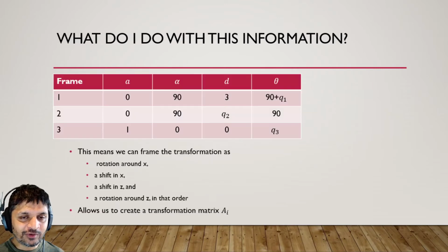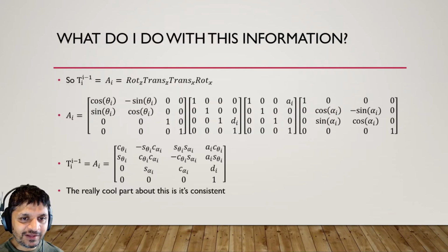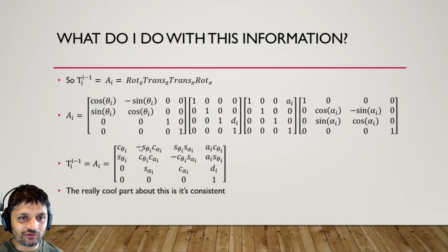Now, here we spent a lot of time talking about how this works and the derivation, well, a little bit of the derivation. The plus side is that in general, you fundamentally just have to have access to this matrix. Either you're memorizing it or you're looking it up somewhere. And then you just work out the Denavit-Hartenberg parameters for your arm, whatever arm it is. You plug it in and you get your transformation matrix. So next week, Monday, we'll be having a TUT that will give you some examples and exercises to work through to actually produce these transformation matrices.